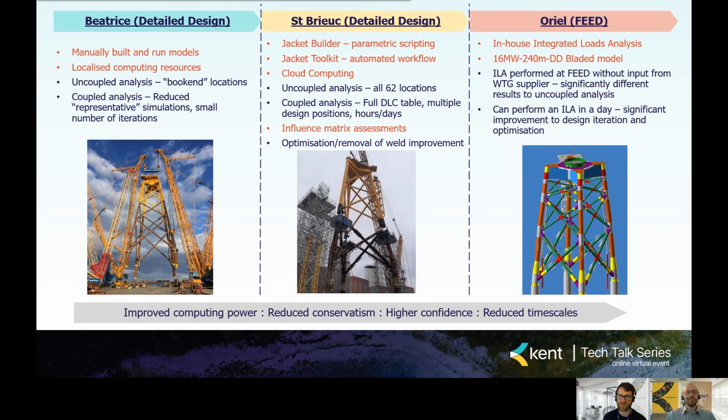And the result of these manual processes and limited computing power was that we had to take a bookending approach to the design. So that was looking at the softest or stiffest locations only in a cluster. And for the coupled analysis, we had to perform a process of reducing the number of simulations to a set of representative simulations, so that the amount of computation was manageable, because the time history analysis that is required for the coupled analysis is very computationally intensive.